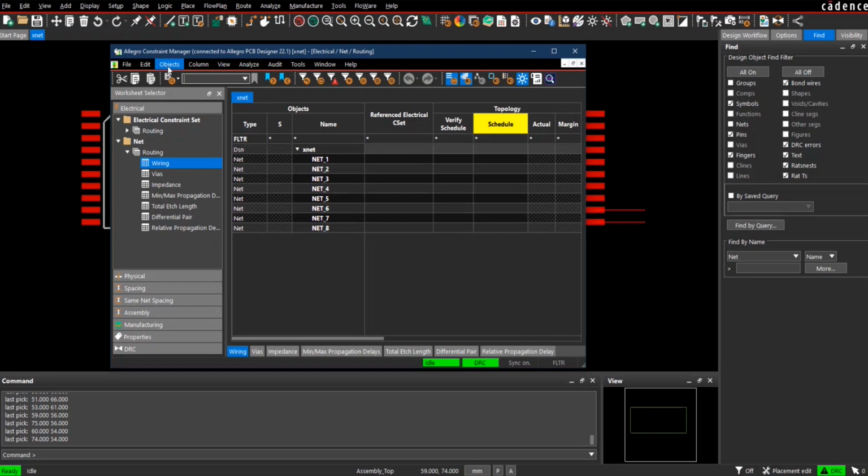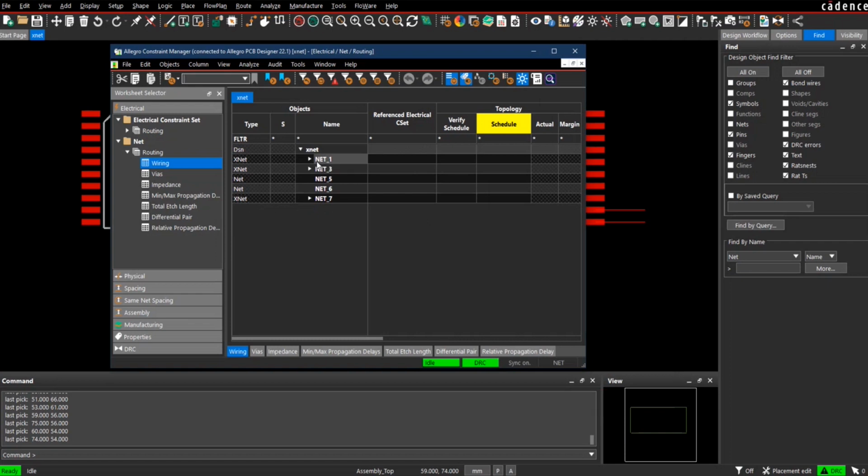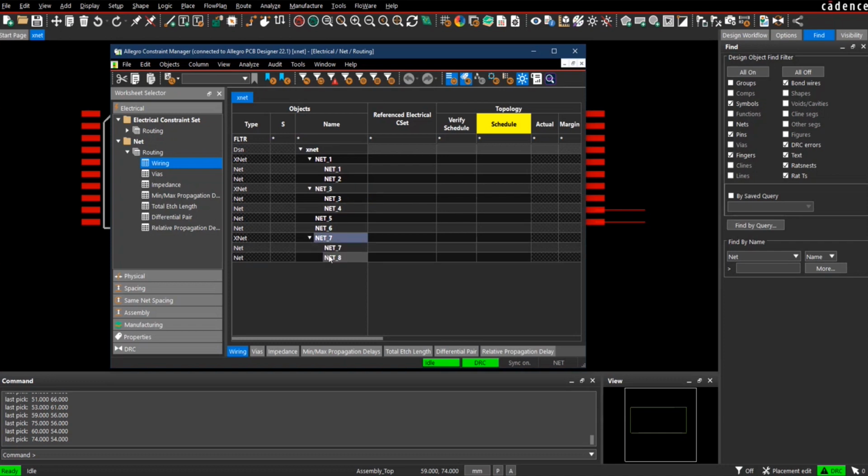And this is really a frequently asked question on the hotline. So if you don't want to use them, simply switch them off, or turn them invisible, I must say. This is more precise. And if we really want to see what's inside of the XNets, then we can also turn the nets inside of the XNet on by "nets of XNet, show net of XNets". And then now we see everything. Now we see the XNet, net 1, and the 2 nets underneath this, and also here.